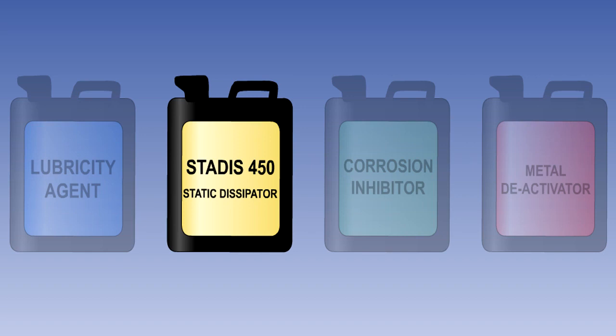Static dissipator additives partially eliminate the hazards of static electricity generated by the movement of fuel through modern fuel transfer systems. This would otherwise be a particular problem with the high flow rates generated during refueling and defueling.